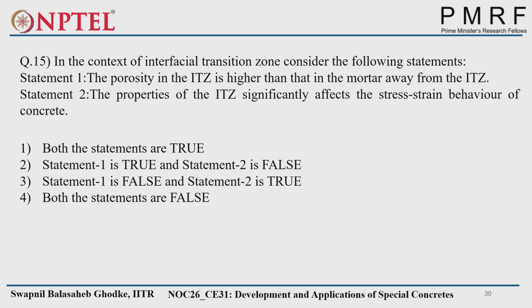So in the context of ITZ, the first statement is: the porosity in the ITZ is higher than the mortar away from the ITZ. And the second: the properties of the ITZ significantly affect the stress strain behavior of concrete. So what will be the answer? Okay, both the statements are true, and someone is saying one is true. Both are true, right?